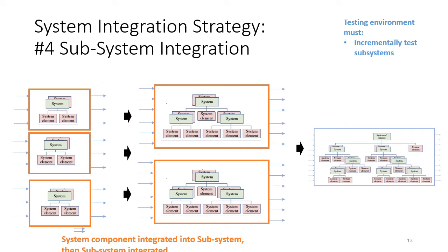Subsystem integration is kind of a more system hierarchical way of thinking about it. You take the component systems, you organize them into subsystems, you test those. Once you've tested the subsystems, you connect the subsystems together and test those, and so on until you've integrated the overall system.